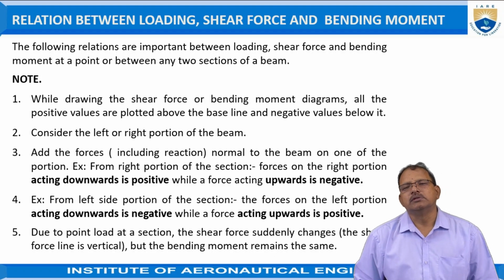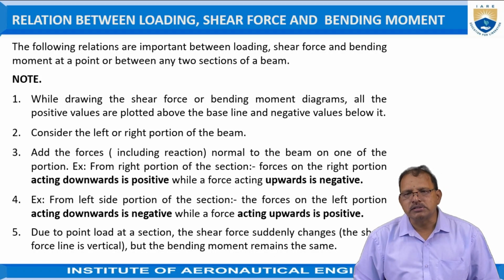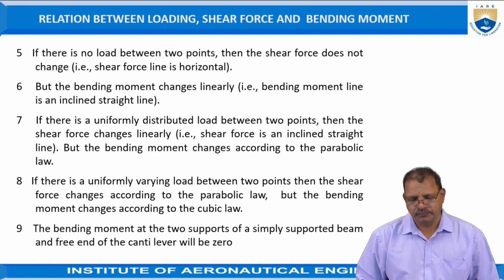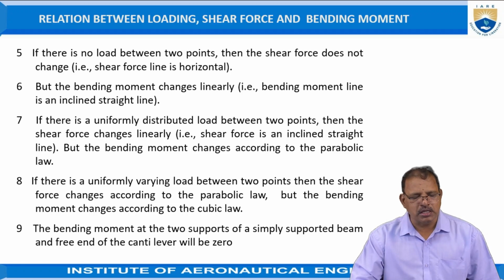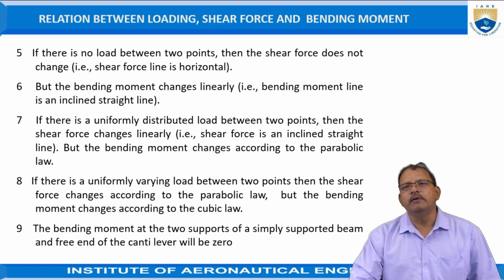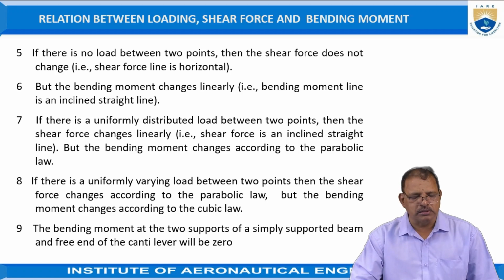Due to point loads, the shear force suddenly changes its sign and value, but the bending moment remains the same at that particular point. If there is no load between two points, the shear force does not change, because the shear force is treated as the unbalanced vertical force. Hence, when there is no force between the two points, the shear force remains constant. But the bending moment is the product of force and distance, hence it changes in the form of inclined straight lines.